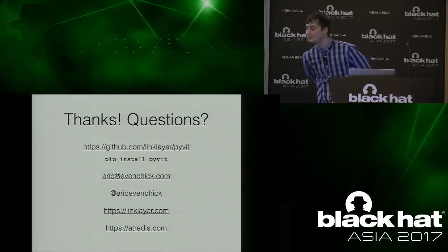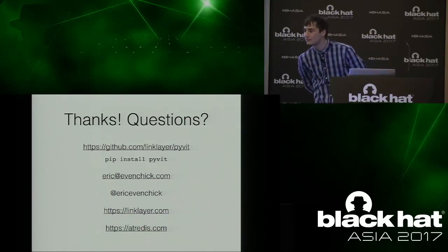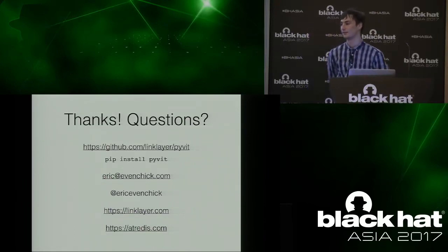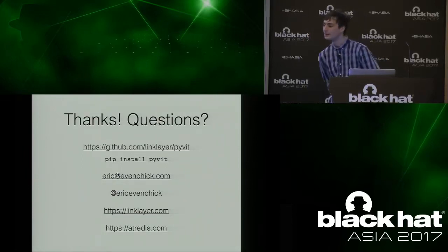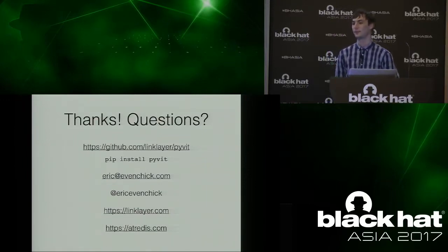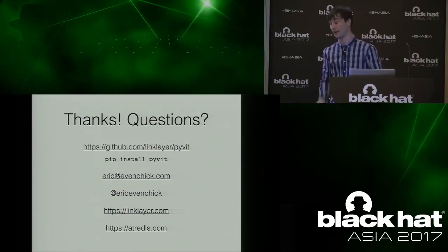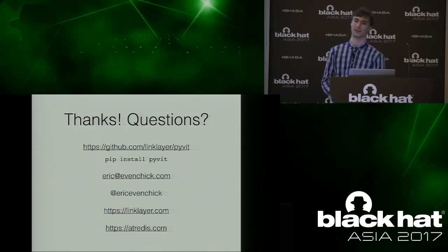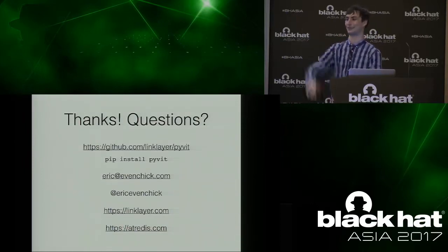Yes? There are tools like Wireshark that allow you to record all this communication and see it offline, like data frames and stuff like this. Or even replay it later. So the question was, does Wireshark or something like that let you record this? And I would really like this to just show up in Wireshark, because Wireshark's great and you can just click things. And actually, Wireshark does have support for CAN. On Linux only, but with SocketCAN, just like any other network interface, you double-click can0 and you're getting CAN frames.